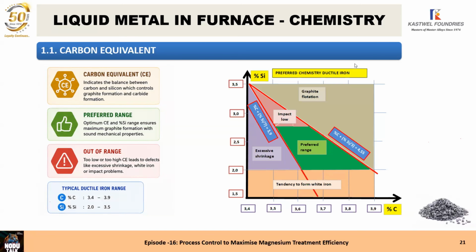And during the transport, please cover the ladle with a blanket or whatever you do. Cover the ladle and bring the pouring spout of the ladle as close as possible to the mold, to the pouring box. Many times, and now I talk about India, I could decrease the tapping temperature by 30-40 degrees C. Many times, but you have to consistently follow the rules.